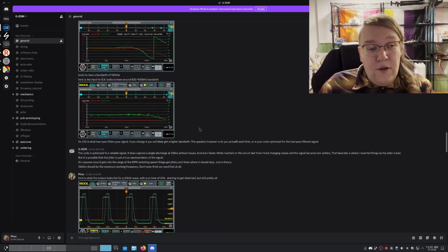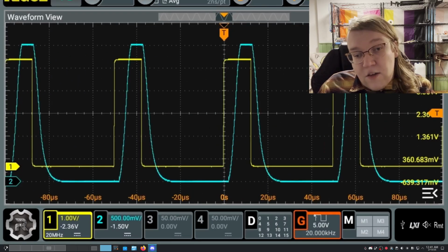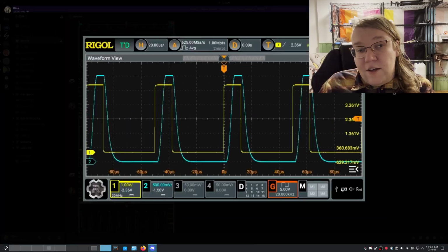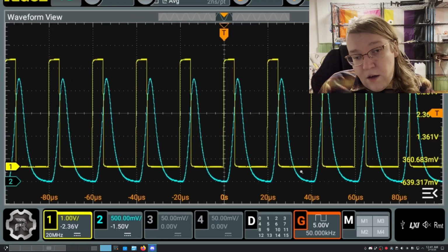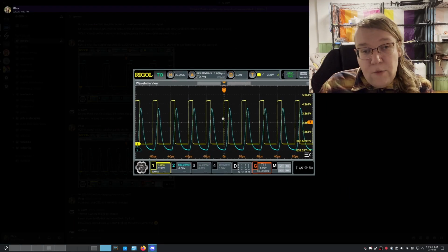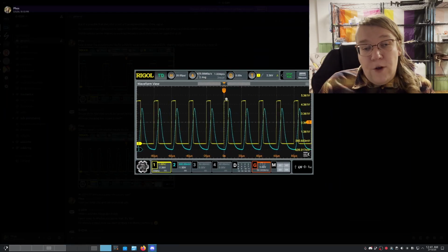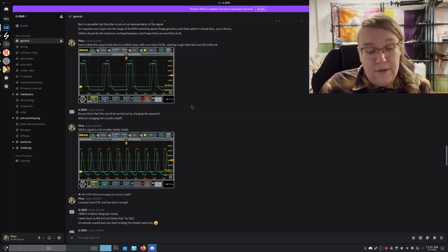maximum bandwidth. And we can see what this does to signals. Here we can see a 20 kilohertz, 25% duty wave gets quite significantly smoothed, and at 50 kilohertz, the same wave is basically just one sharp spike and loses all resolution as well as what the actual voltage is. So we discovered the bandwidth limitation of the existing signal path.